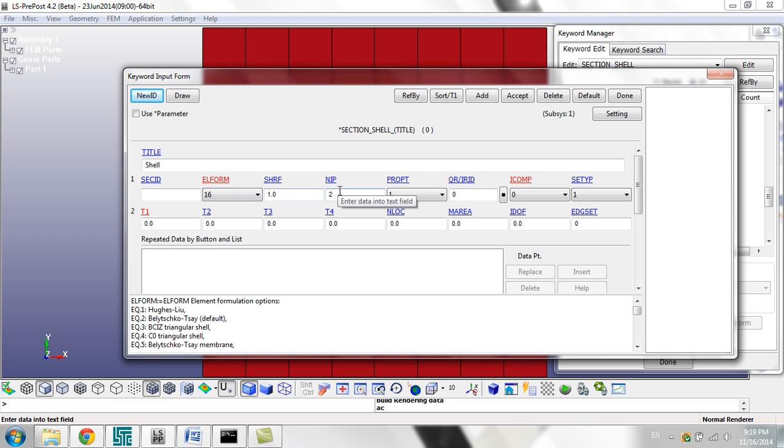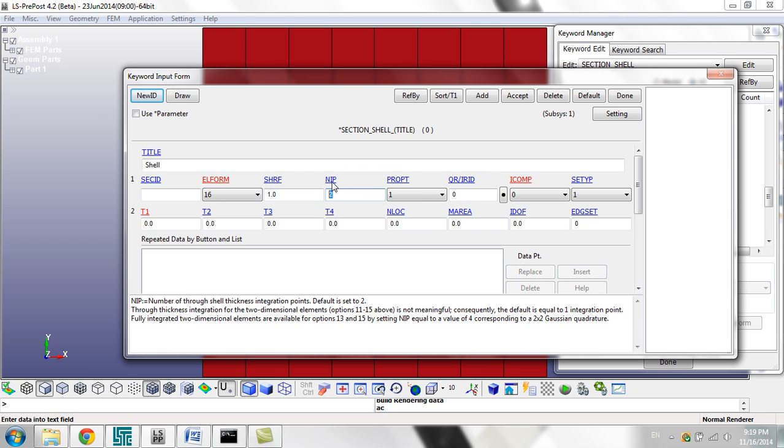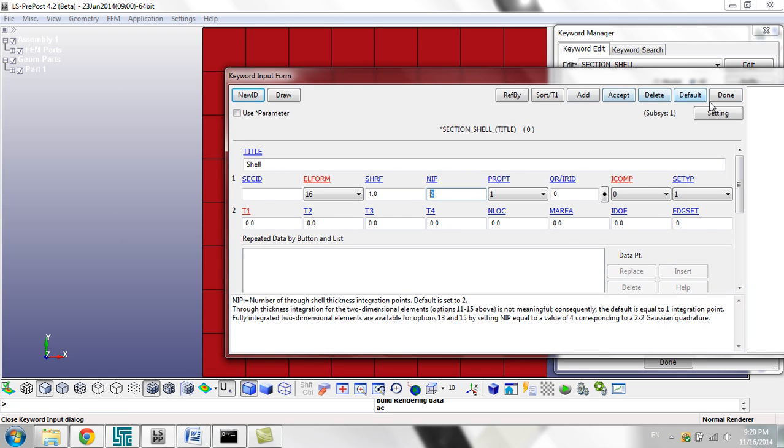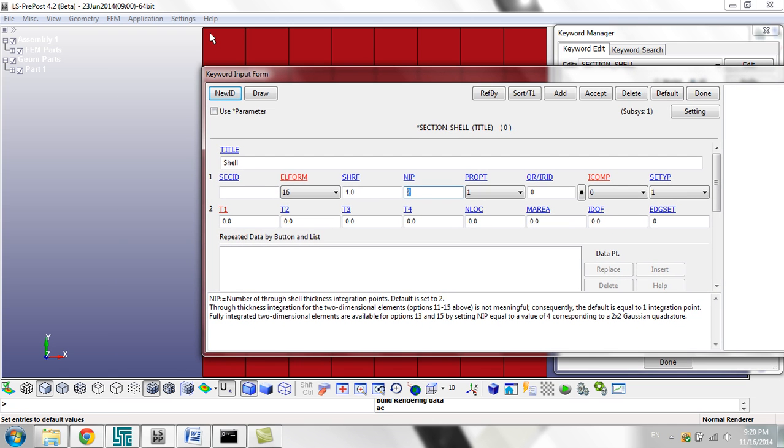And now after that, we will go here to the number of integration points. This is splitting. For example, we are dealing with a shell element. If we go here for the shell element, you will find that the shell element has no thickness. This option asks you how many divisions you want to divide your thickness into to make the integration. Most manuals recommend using number 5 for elements. If you want higher results, higher output values, you can increase this value, but a 5 integration point is enough for us to have very good output.